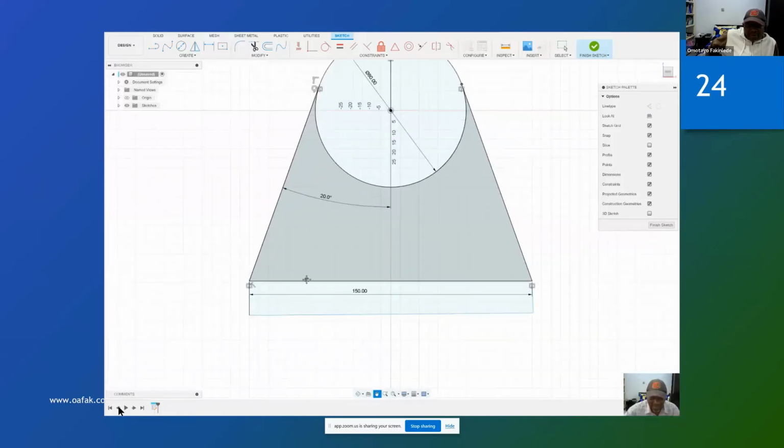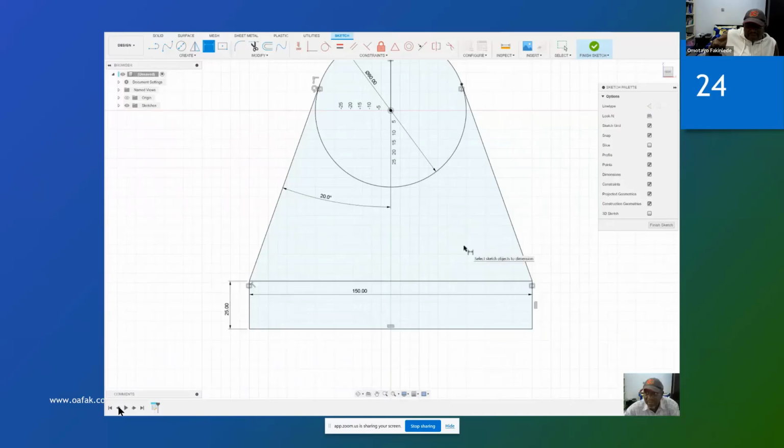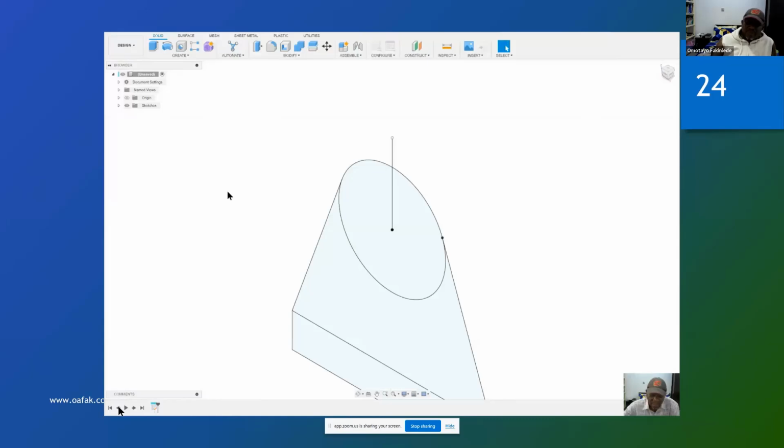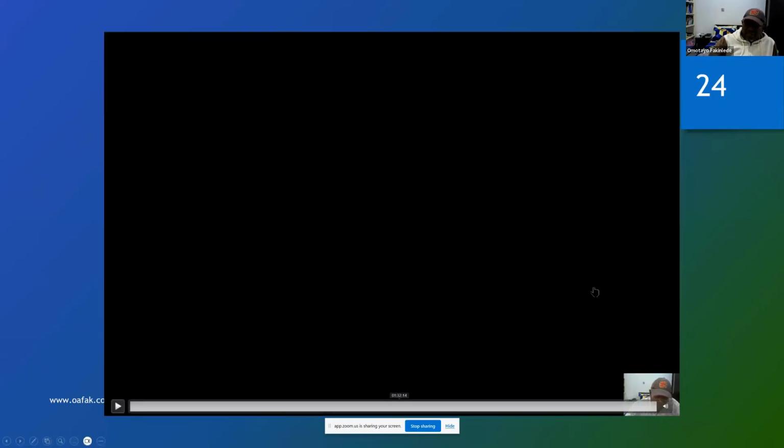Okay, and then with the pan handle, you can now make sure that the dimensions are there. The dimension of the vertical side is 25, but you want to constrain it to be horizontal and vertical. The person who asked me to demonstrate horizontal and vertical constraints must have been sleeping in class, because we've been doing that every time we draw something. So that's 25. The only thing I forgot is that line should be removed. Okay, so that's it.